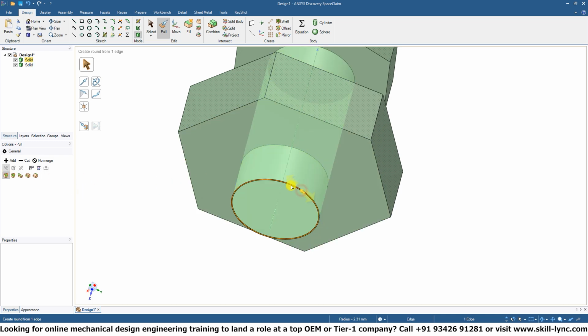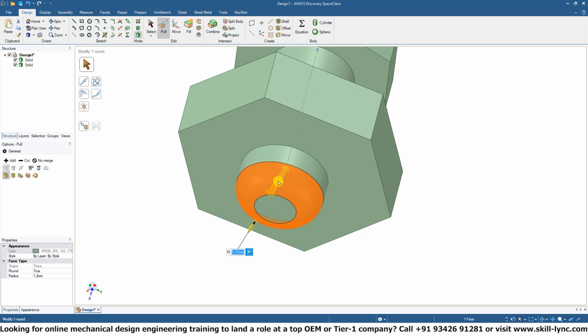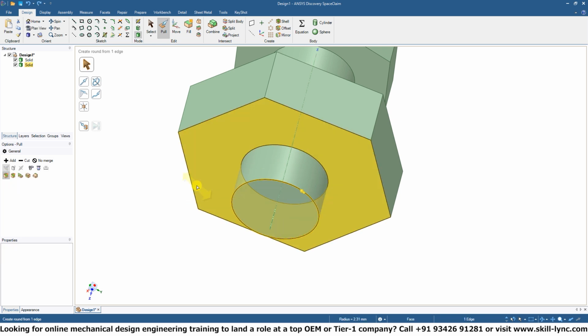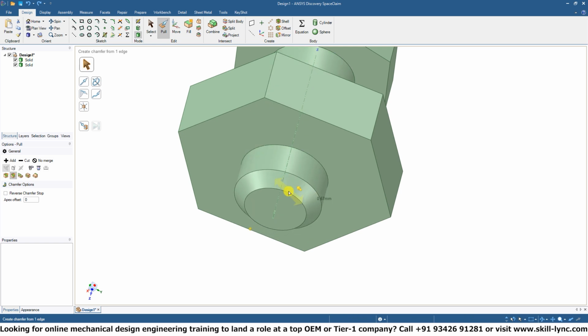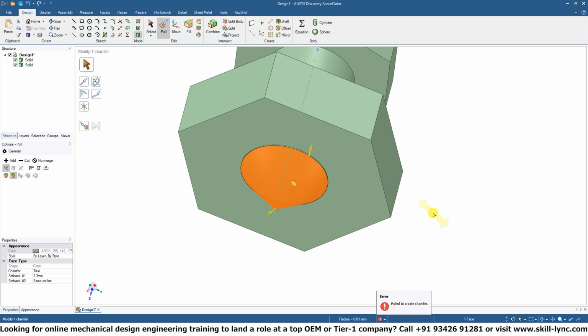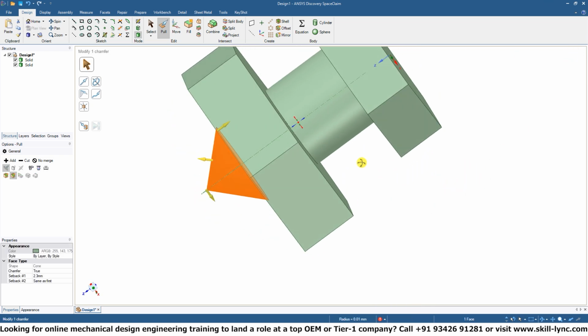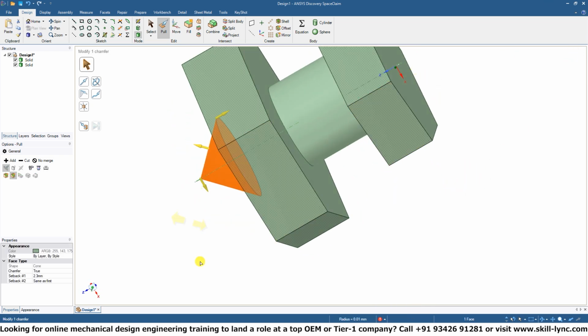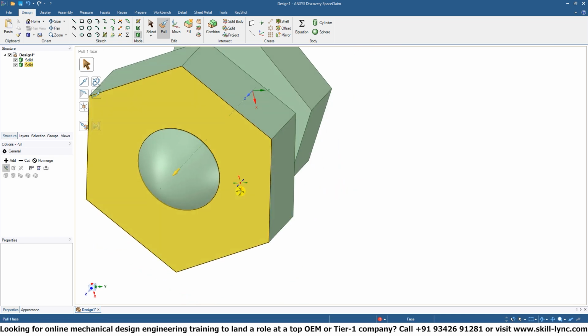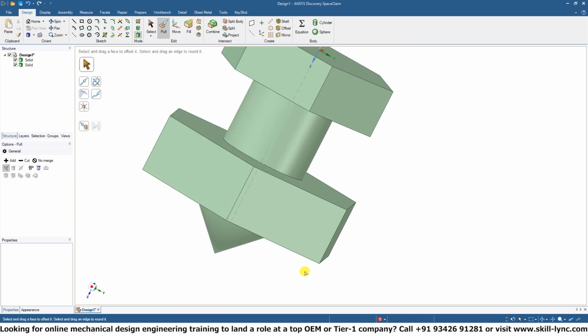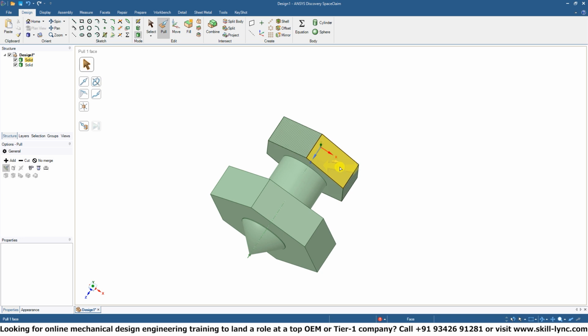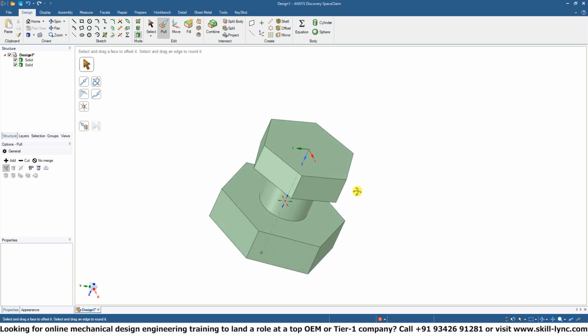You have some leeway to help the bolt go in. You can add a fillet over there, or more so a chamfer. In this application, you can do it that way if you wanted to. That would help from a mechanical engineering perspective or from a design point of view. It would help you locate your bolt through assemblies or through pieces.